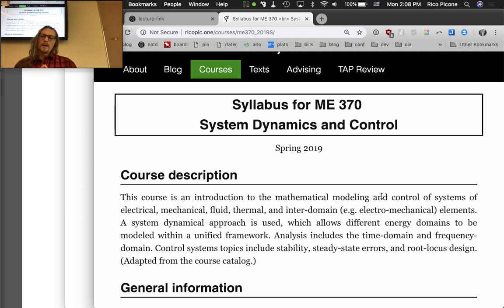And these equations describe the dynamics of the system to us, along with the constraint equations, the equations that we use to describe how those elements are connected. So those would be the continuity and compatibility equations, which were like the KCL, Kirchhoff's current law, and KVL, Kirchhoff's voltage law,